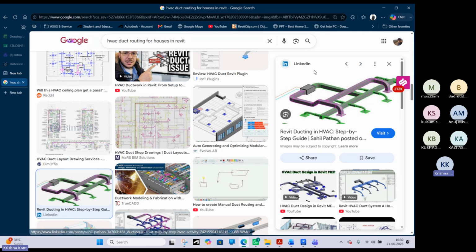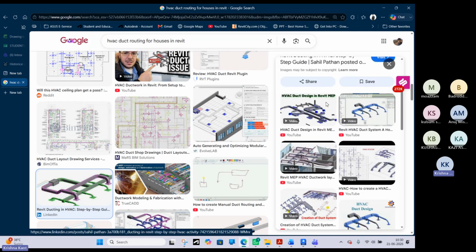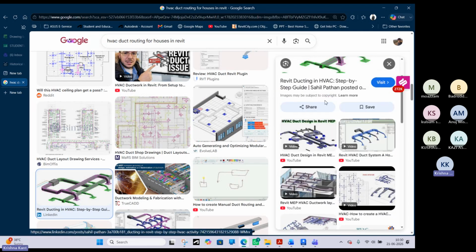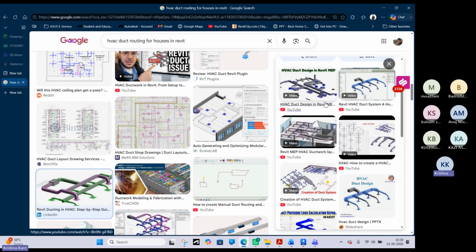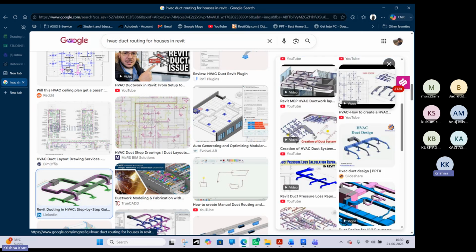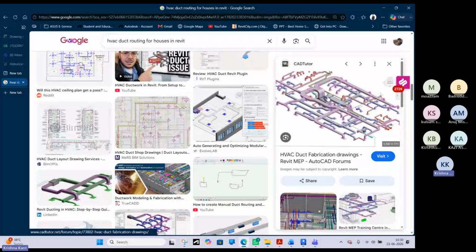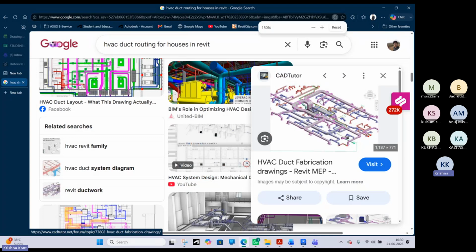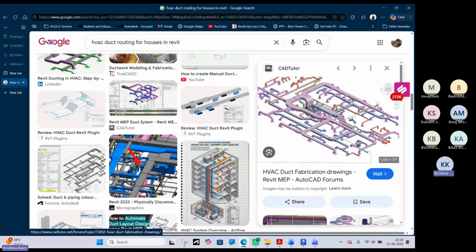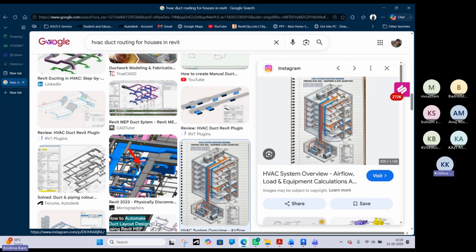Also, wherever we provide the central duct, we require more ceiling height. So make sure, obviously in commercial places we have more height, so we can easily work on it here. In bigger projects, there will be lots of ducts and all, so everything will not clash. It will be clash free. So the ceiling height should be more. Now you can understand how this HVAC works.